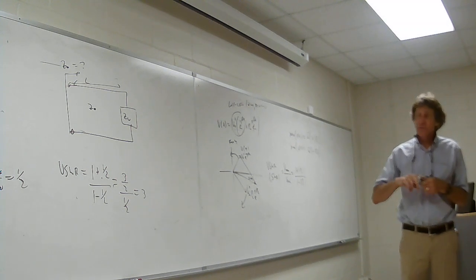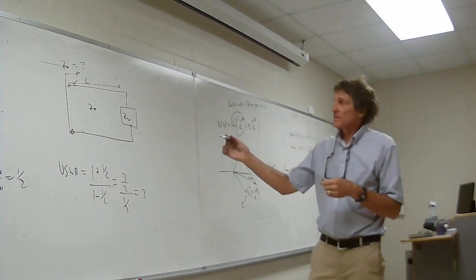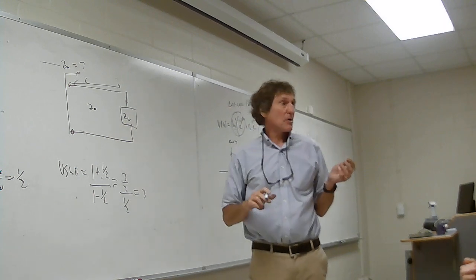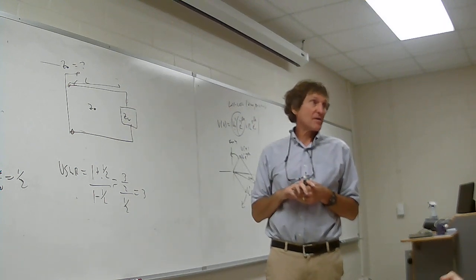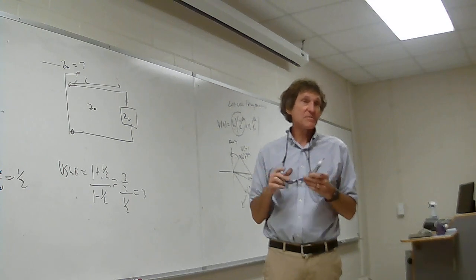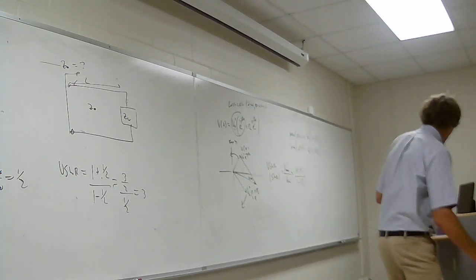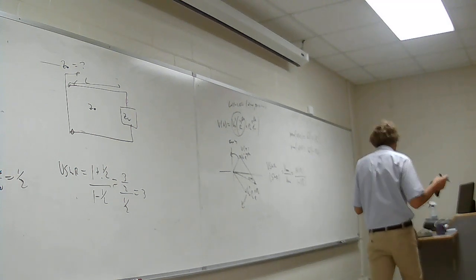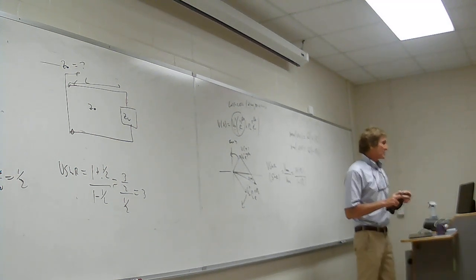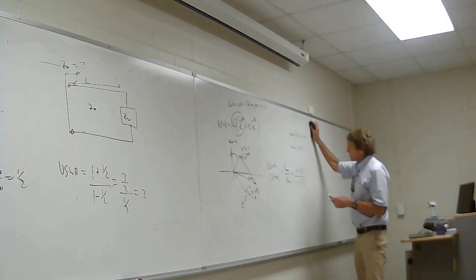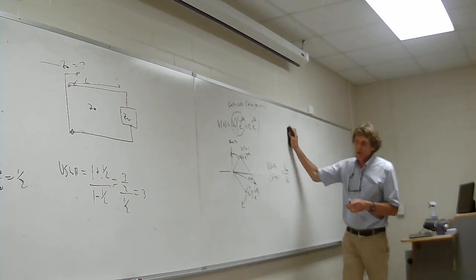It had to do with an impedance mismatch. Basically, this and this were both 50 ohms. There was a big old solder ball that put about 70 ohms there, j70 ohms, just enough to destroy everything that I've tried to do. I don't know if it was 70. I know it was enough to cause me heartache about it. So that's what standing wave ratio is.